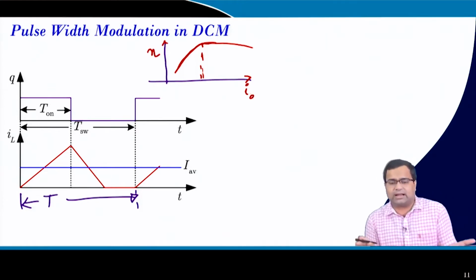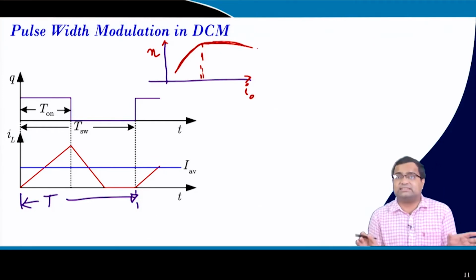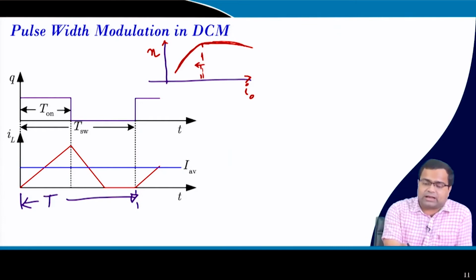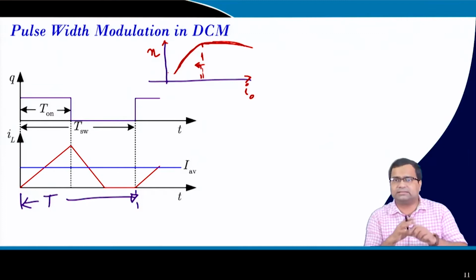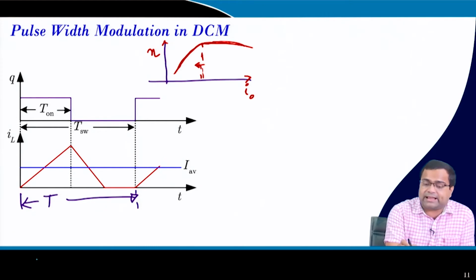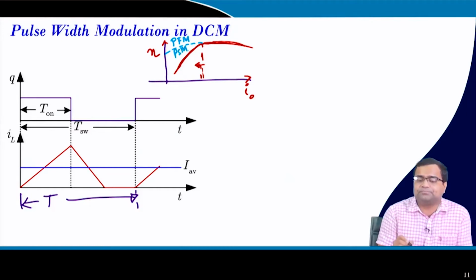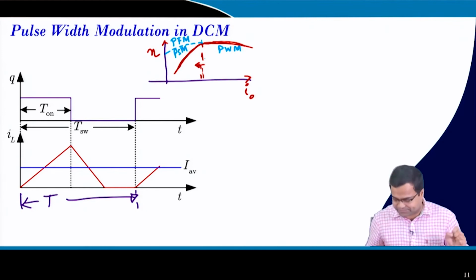So, if you increase the load current, the efficiency will decrease slightly because at higher load current your conduction loss increases. But if you decrease the load current and maintain the pulse width modulation, your switching loss dominates and your efficiency can fall drastically, and this is not acceptable. So, in most commercial products they extend it by means of PFM, sometimes pulse skipping modulation, but at heavier load it is operated in PWM. So, there is a multi-mode scheme, that means two control techniques are merged together.